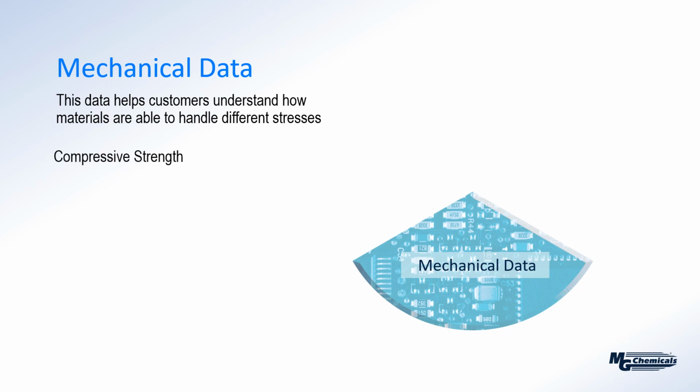Next, let's look at the compressive strength. Compressive strength is the opposite of the tensile strength: whereas with tensile we try to pull something apart, with compressive strength we try to understand how well a material resists being crushed. So we make a cylindrical block and place it between two cylinders. We hit play, and it continues to move in on the sample until the sample yields.